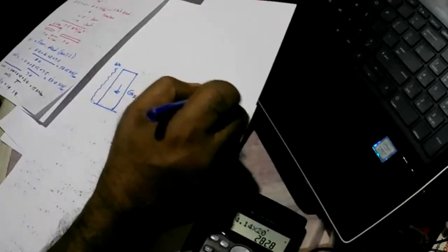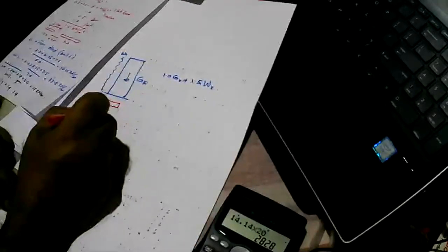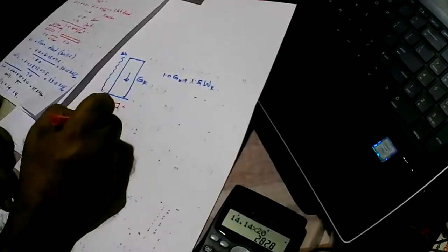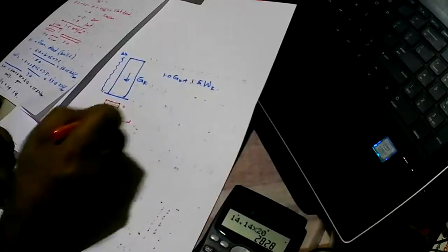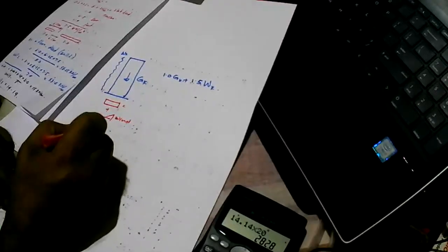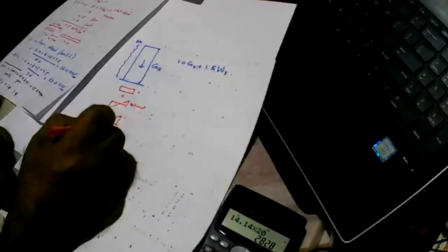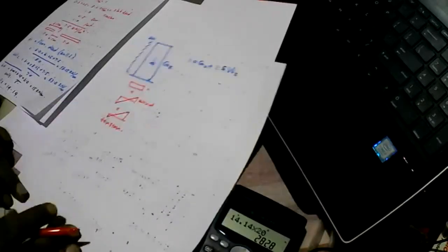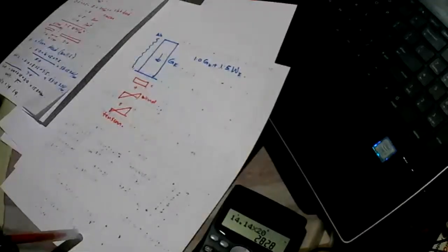So what happens? Minimum dead load will give a stress distribution like this, and compression, this will be like this, wind, and there's a possibility that we'll end up with something like this, where we get tension. And tension here can uplift the foundation. So this is one of the critical cases that we have to consider. So we call it combination number 1.